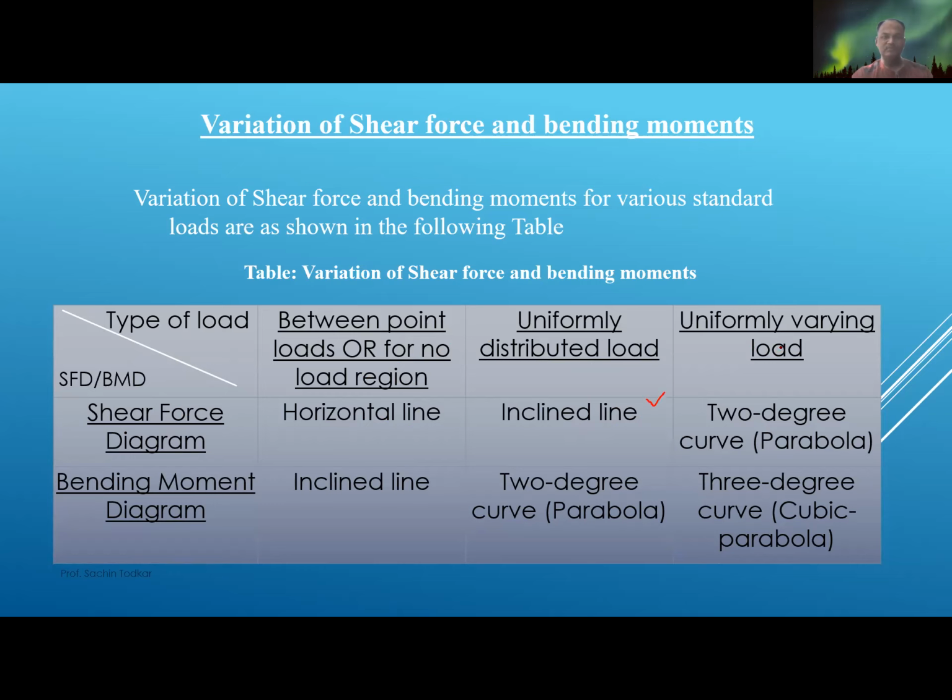And if the loading is uniformly varying load, it is a parabolic loading condition. So in case of parabolic loading condition, we will get a 2-degree curve or parabolic curve in shear force diagram and a cubic parabola in bending moment diagram.